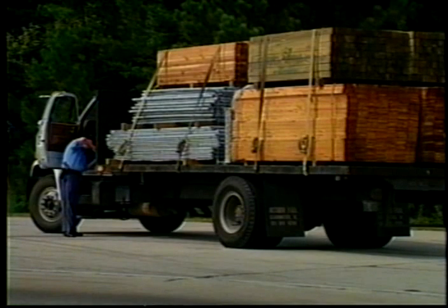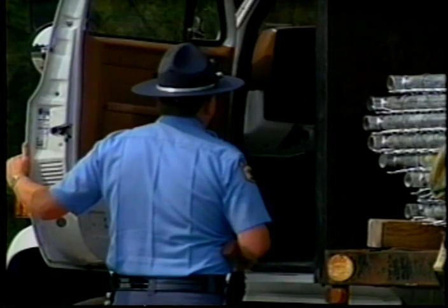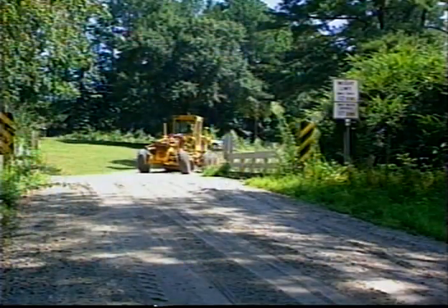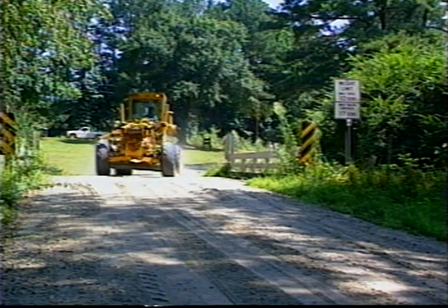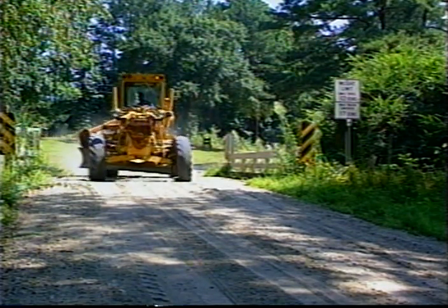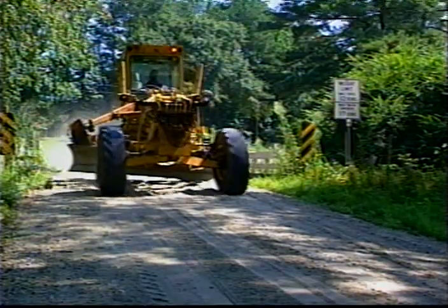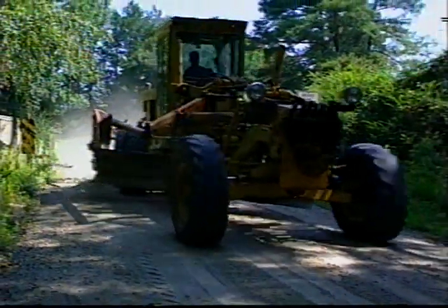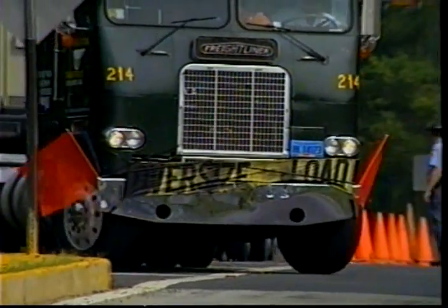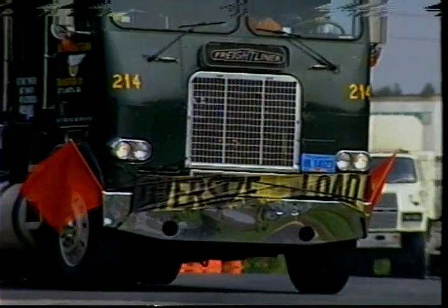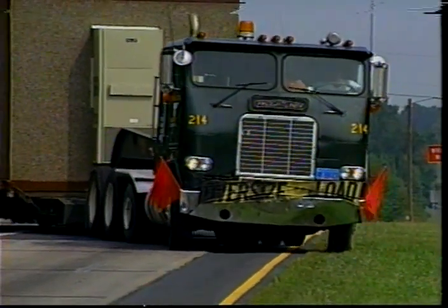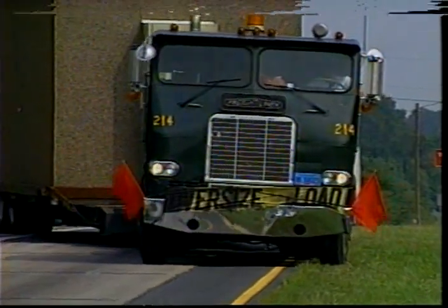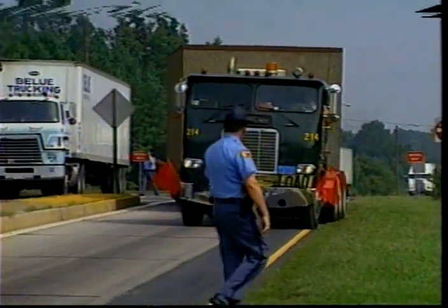Enforcement of posting is very important. Many bridge failures have occurred because excessive weight vehicles used a posted bridge. Almost 50% of the bridge collapses resulting from live loads have involved posted bridges. This alarming statistic indicates that many drivers either did not know the weights of the loads they were carrying or ignored the warnings. Some over-limit loads, however, must still be transported. For this reason, all states use permit operations to control these shipments. The primary objective of these operations is to avoid safety hazards to motorists and protect the structural integrity of the highway system.